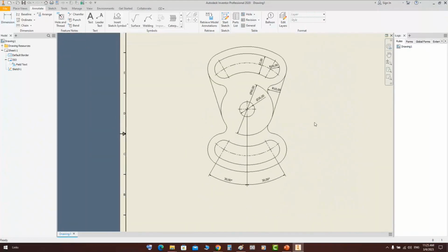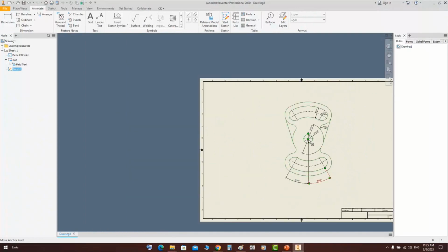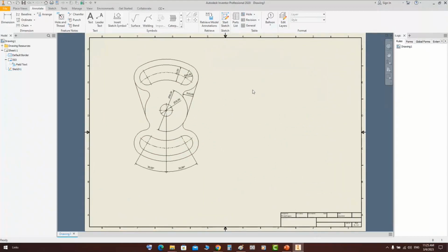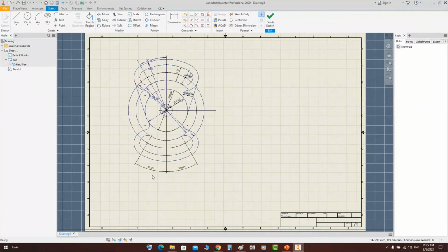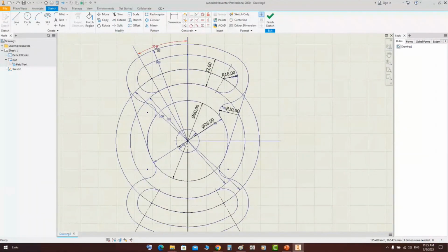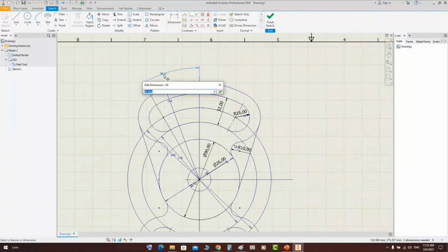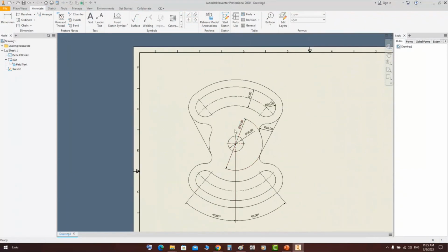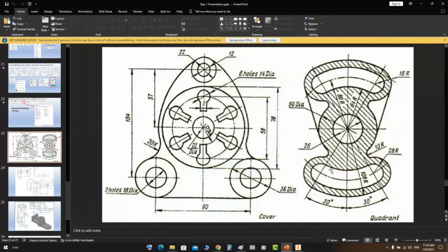So you can define your sketch by that way. You can move it anywhere like that. So you can use the drawing part as AutoCAD, and anytime if you would like to make a change, just come back to the drawing again. For example, if you would like to change this angle to 40 degrees, when you click finish, automatically the values will change. So it's a flexible sketch or a parametric sketch. You control it by using features. How to change it?